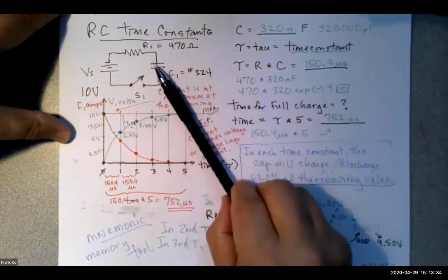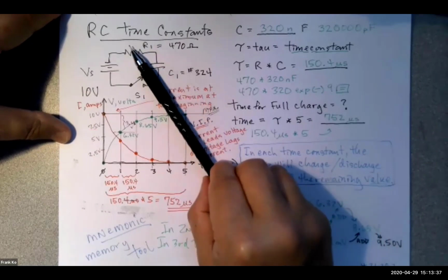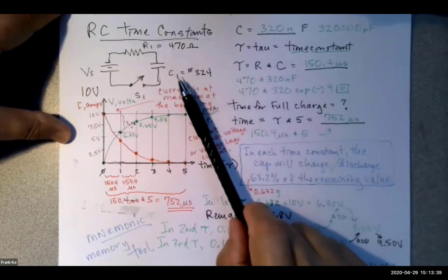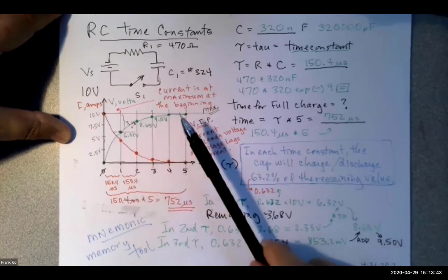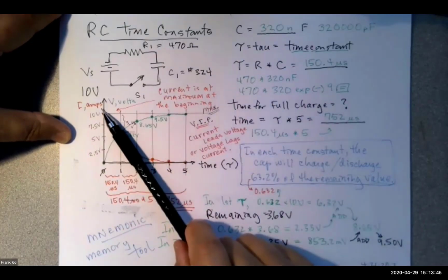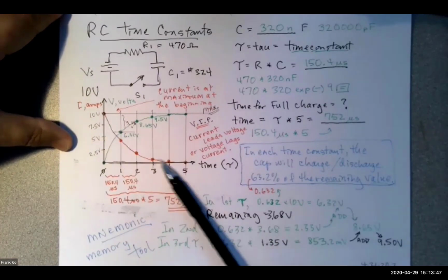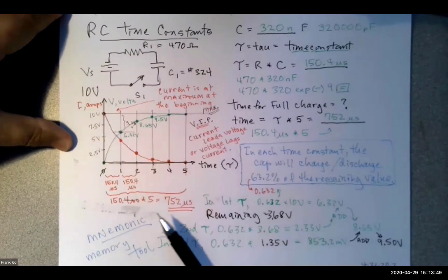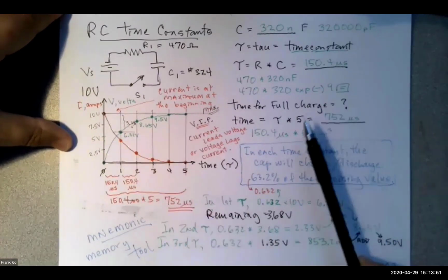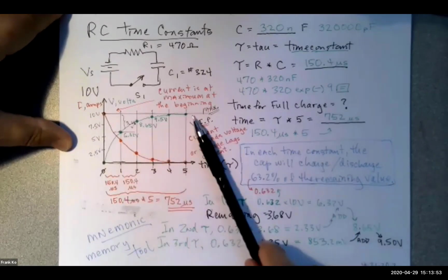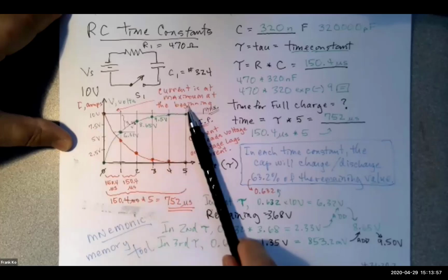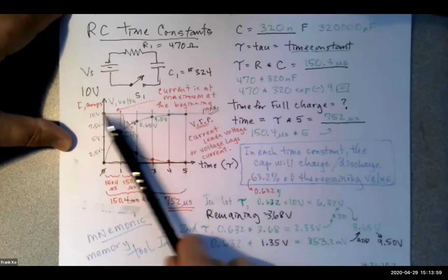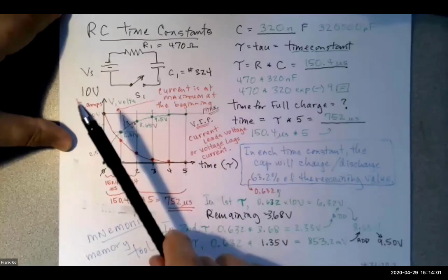When we have a capacitor and a resistor, the capacitor takes some time to reach full charge. The capacitor's current starts at maximum and drops down to 0. And all this happens over how many time constants? It takes 5 time constants to reach a full charge. So that clearly shows that the current and the voltage are not in phase with each other. Current is at maximum